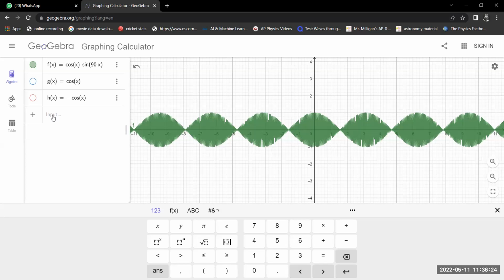So you first modify the light wave as per the input sound wave, and then we transmit. After the modification is done, we transmit it. It goes through the air, vacuum or whatever, and reaches the receiver end, and we demodulate. So demodulation is the method of picking the peak value and then reconstructing the message. Then the message is reconverted into sound using the speaker, like the diaphragm.